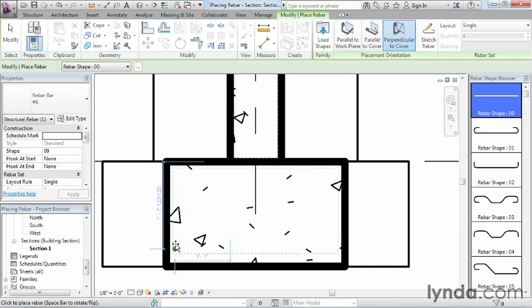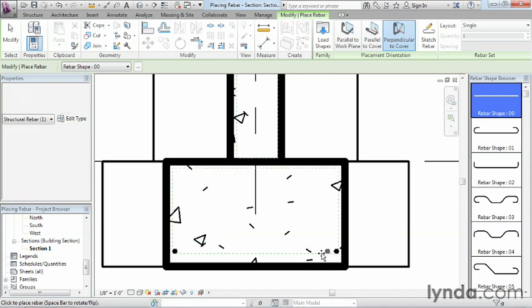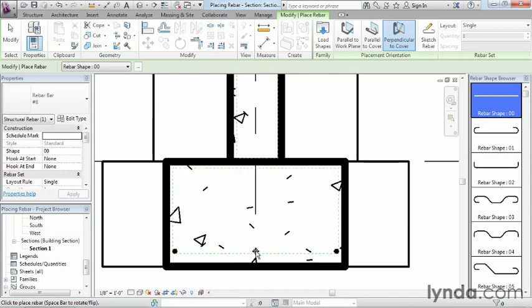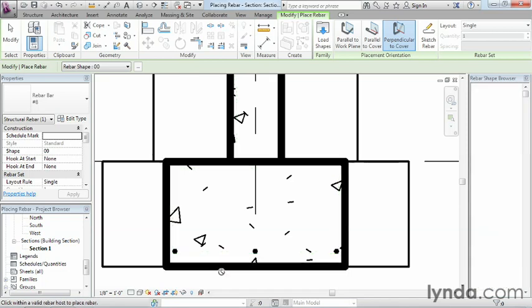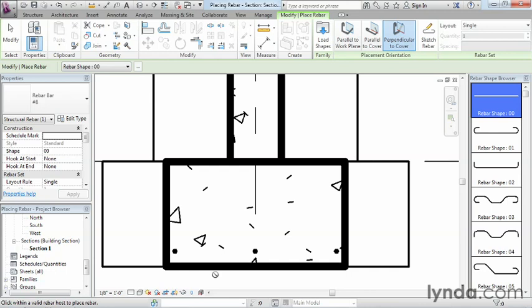And you can see that that rebar does not want to go outside of the cover location. So we'll just go ahead and place it right to the outside edge of this cover here, right to the outside edge of the cover here. And then there's really not a snap tool for this, so we just kind of have to eyeball it, and we're just going to place this rebar roughly right here in the middle. Now we have 3 pieces of rebar, and they're actually 3-dimensional, and they're going back as far as this foundation wall, or in this case, this footing, happens to be drawn.